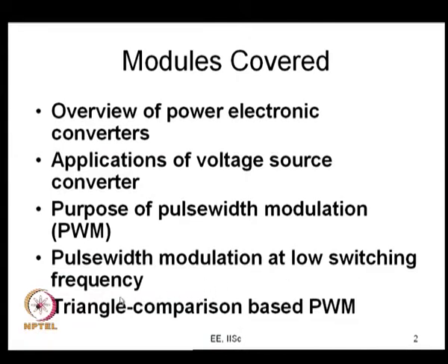We considered the situation when the voltage source inverter switches at a low frequency. Why? Firstly, this was very relevant a few decades back, when the power semiconductor devices available could not switch at very high frequencies; they switched at rather low frequencies, something like 400-500 hertz. But the modern devices switch at much higher frequencies. Nevertheless, this is still relevant in certain contexts such as high power drives.